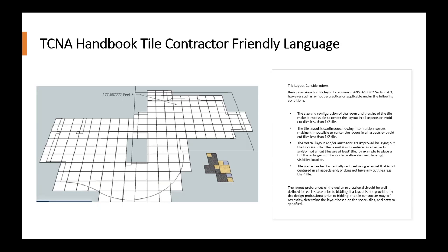And also tile waste can be reduced quite substantially depending on the layout, if that layout is not centered. And so in the case of today with gauge porcelain tile, there is no way you're going to center all that. That makes no sense. If I've got a large doorway, I've got to create an L shape. I need the largest piece of tile around that L shape just for strength.